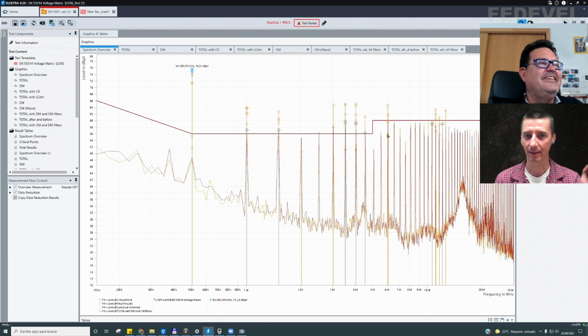So basically the cables, even the cables which you use in your setup, are they some kind of standard? No, the cables I am using are good quality coax cables, but it depends on your work. Obviously, if you want to have a very good laboratory with controlled results, you will need a good coax cable with a good transmission line with good 50 ohms, with good shielding, with a high coverage in the shield, with good connectors and good materials in the connectors, and this will be expensive.